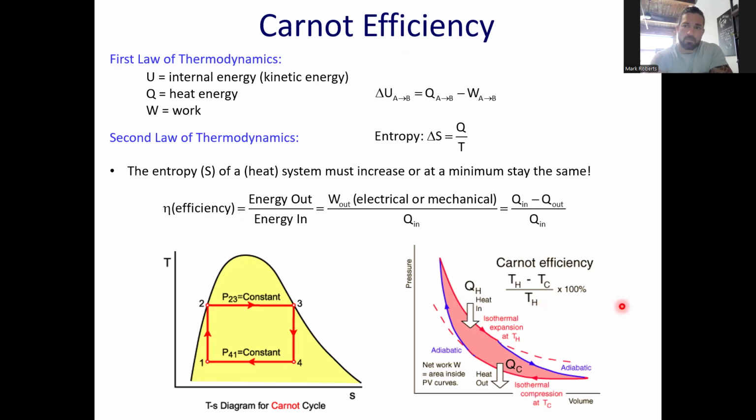And what's important to know? What are the units that you need to use on these? Can you use Celsius, or Fahrenheit, or Kelvin or Rankine? I'm not sure. Well, I think you know the answer to that. I'm asking because in this case we just need to use absolute units, so absolute measurements of temperature like Kelvin or Rankine.